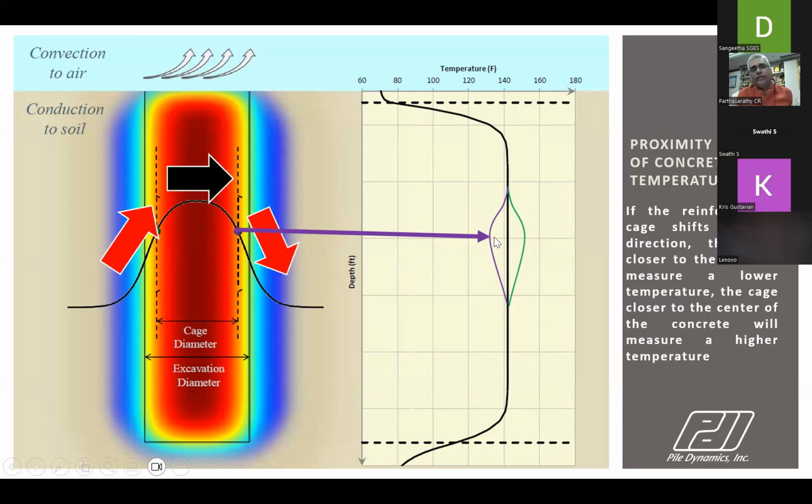Okay. When you see the opposite wires having a warm and a cool temperature, this indicates an alignment issue of the cage. Because the dispersion of the temperature is from the center radially outwards along the shaft, except one diameter towards the top and one diameter towards the bottom.